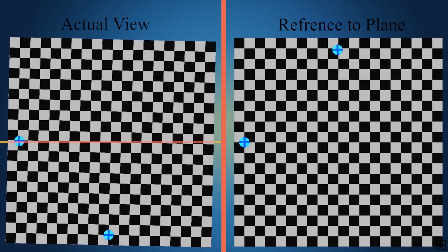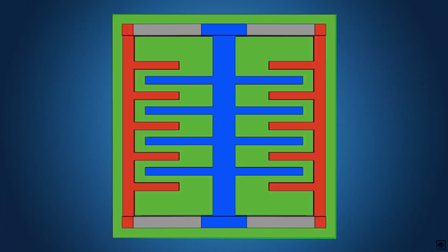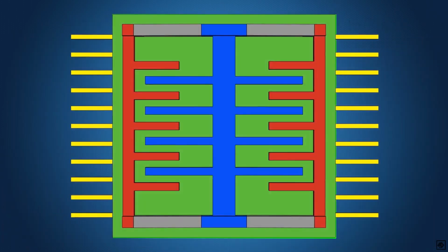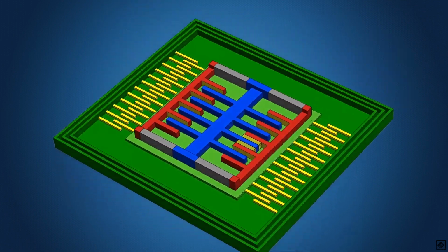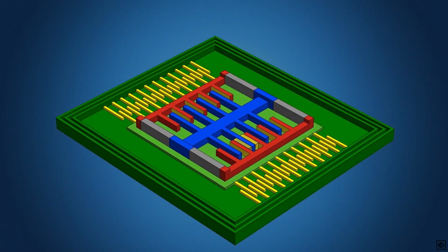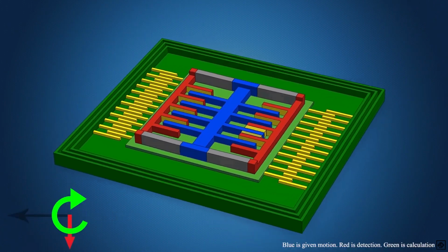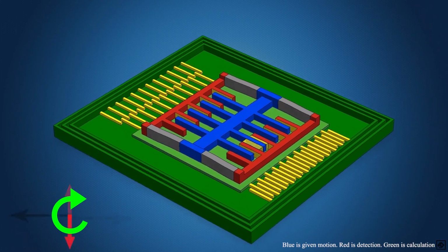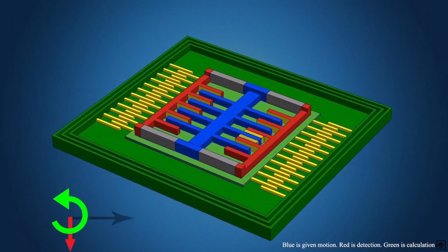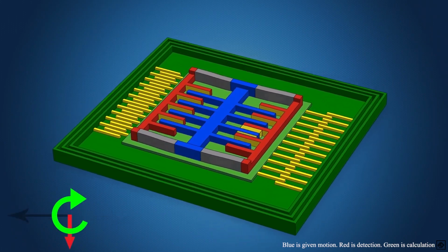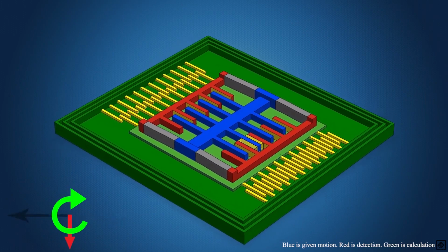And to detect acceleration we use an accelerometer. Gyroscopes are made by suspending an accelerometer on a platform. The platform is oscillated with the help of solenoids. So when the frame is rotated, due to the Coriolis effect, the proof mass in the accelerometer deflects. This deflection is measured and processed by the circuitry, then converted to a 0 to 5 volts signal.